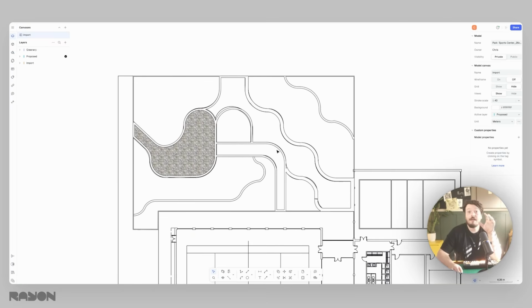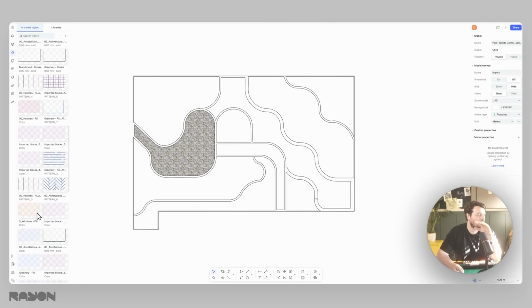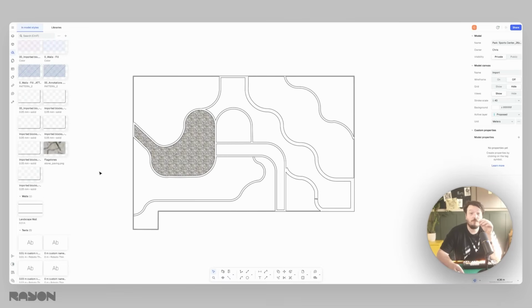is seen. Okay, so I've just spent a little bit more time tracing over those wall elements, and I'm just going to turn off my background so you can see it cleanly. So you can see the different thicknesses of walls that I've set. So I've got one style which is 300mm, one style that is 100mm, and one style that is 600 to show those different thicknesses, and they all live within my wall style tab.